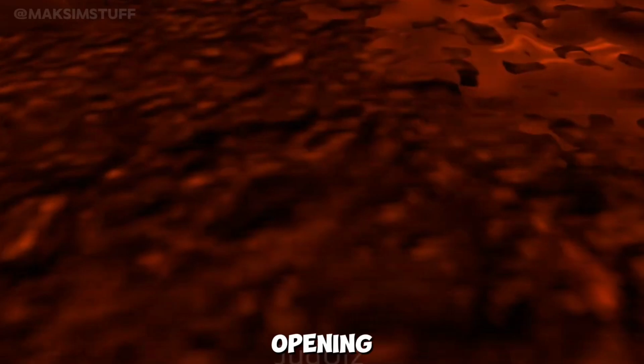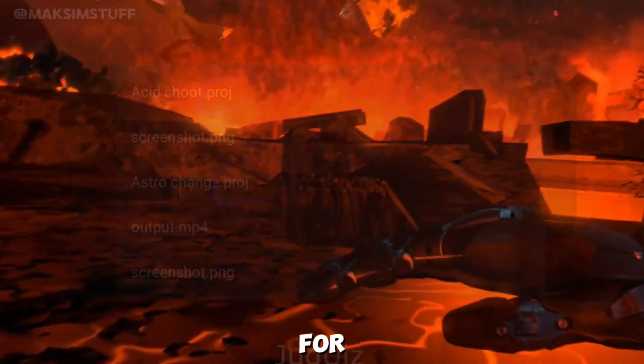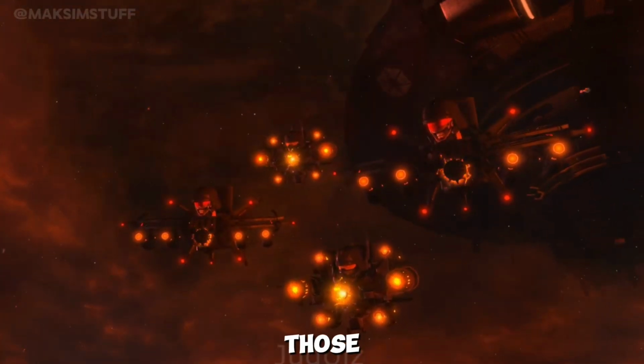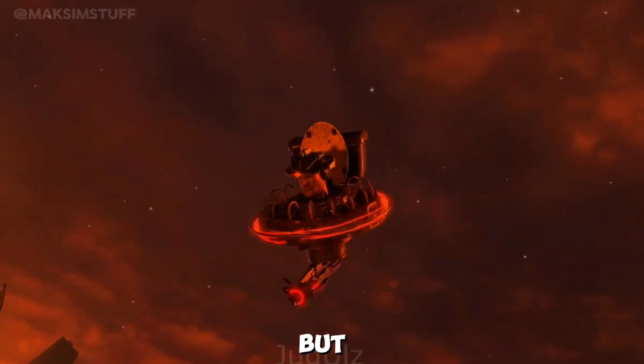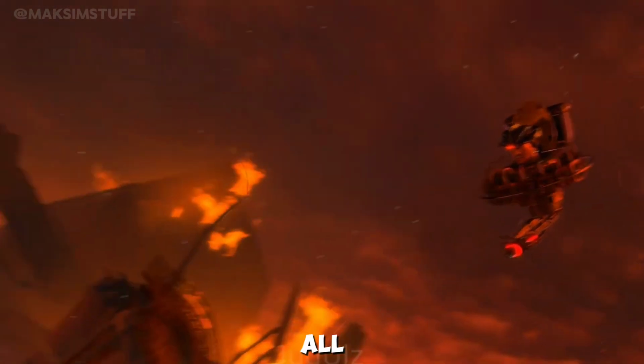First, let's go over the most common mistakes. The first and most common problem is habit-based importing. People are used to opening an archive and trying to import files directly from it, usually looking for files like .proj. So they open the archive, try to find those files inside it, and tap on things hoping it will import. But the problem is there are no .proj files in this pack at all.